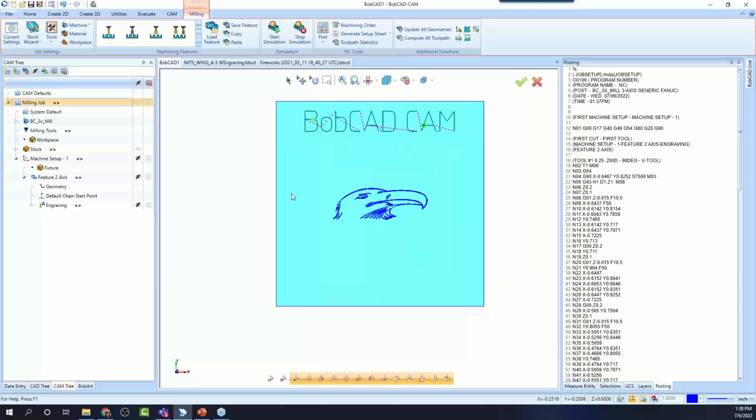Okay. All right. So we got our job set up. We picked our machine. We set our tooling. We have our zero position. We have our stock. We have a feature. We got some toolpath on the screen. We adjusted our feeds and speeds. We posted code. We ran the program. Everything is good. Now we want to use this same format, but we want to apply it to different geometry.